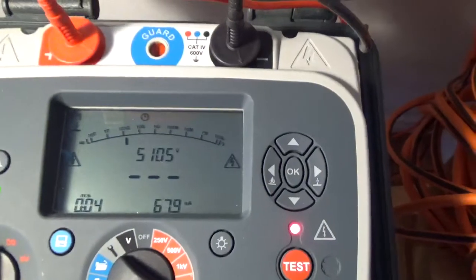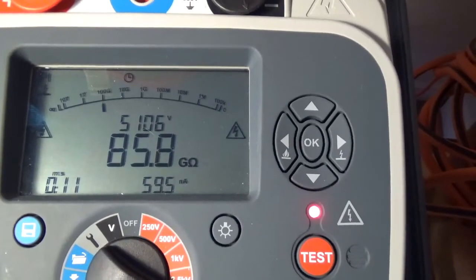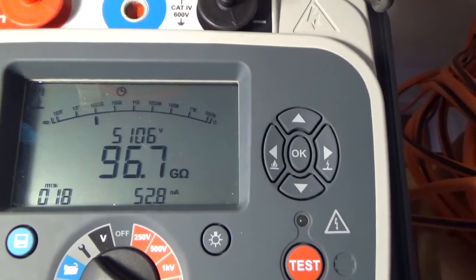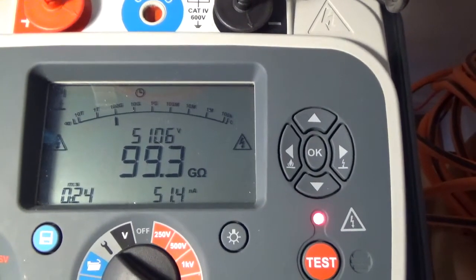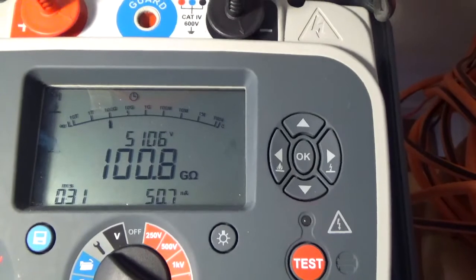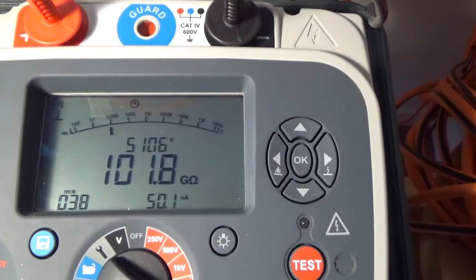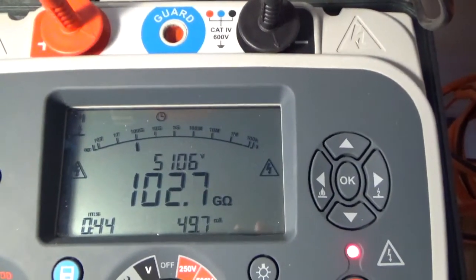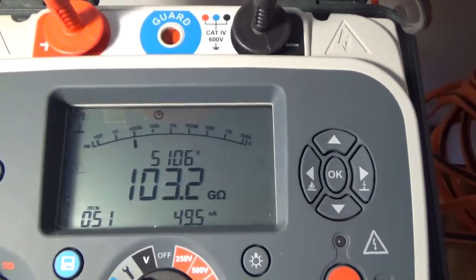Okay, I'm going to zoom in on the screen a bit, so you can see the timing at the bottom. It's taking note of the timing. You see the voltage level it's at now, 5106. You see the current leakage around 50-some nanoamps, and it's using that to give you the gigaohms. We're at the 28, 29, 30 second mark. When it gets to the 1 minute mark, it's going to capture the insulation resistance and hold it, then wait till the 10-minute mark and capture the insulation resistance there, and then you'll see the polarization index displayed on the screen. So we'll cut away here so you guys are not waiting.